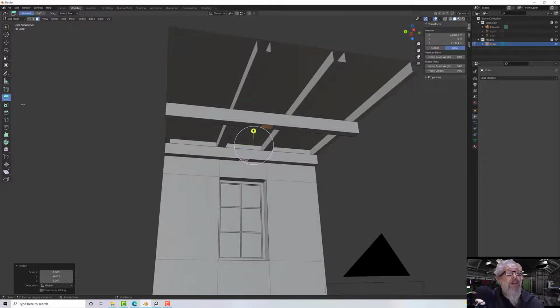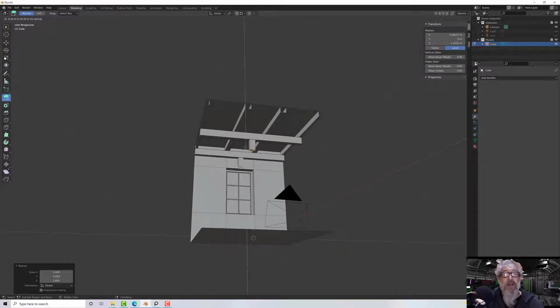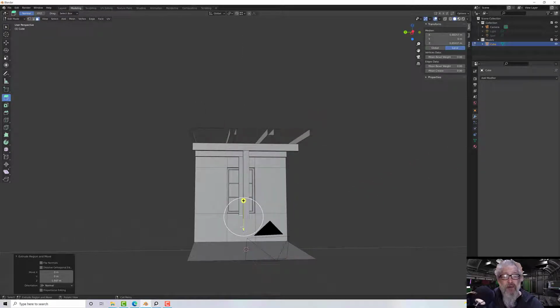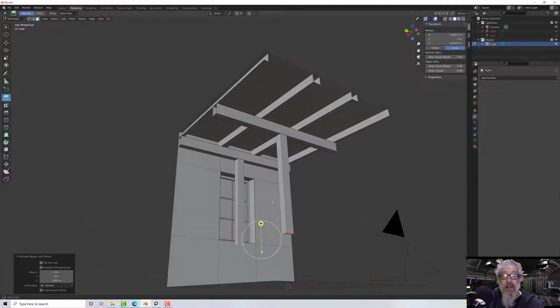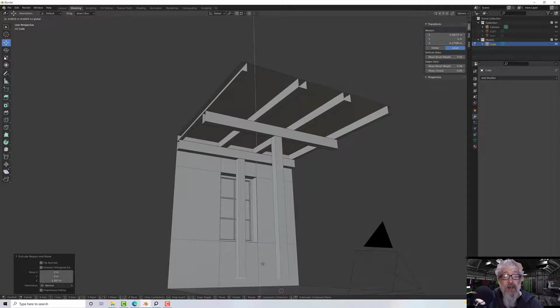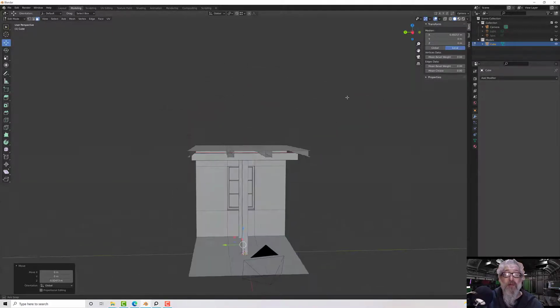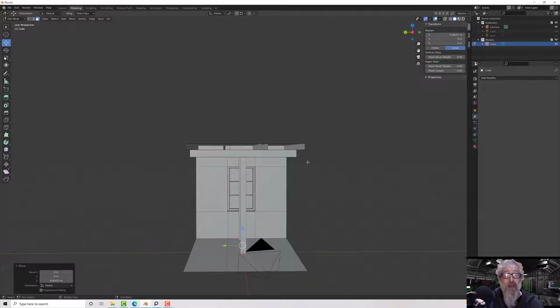And then we'll use extrude and bring it down until it hits the floor. Actually, I've stopped, so it will do it again now. So I'll just hit G rather and pop that down. Because scale is correct, we should be able to just press 0 in the global transforms there, and that should do the job.